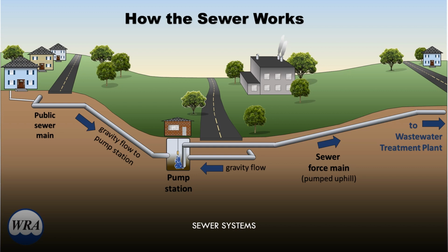However, if your house is actually below the elevation of the treatment facility or needs to travel uphill or over a hill or through mountains or anything like that, you would have to use a grinder pump or a lift station. A lift station essentially pumps sewage from low elevations up to the sewage main line so they can continue out and into the wastewater treatment facility. And these pumps are specifically designed to handle large amounts of solids like waste or toilet paper or flushable wipes.